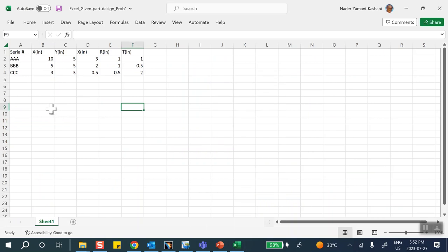Okay, or this is what I mean. Notice that you specify your units by putting it next to whatever you've got. For example, if these are length, you put inches or millimeter, whatever. But when you create the parameter, do not call that parameter big X parentheses IN. Leave that IN out. That's what I mean.